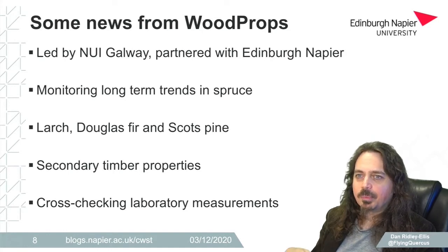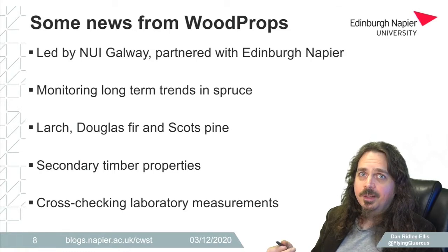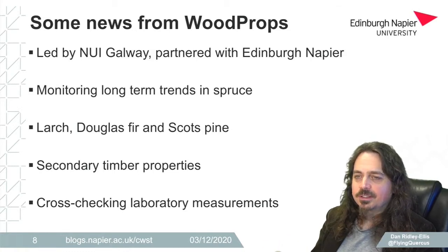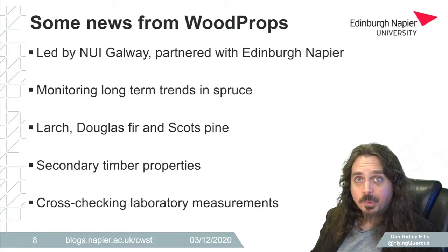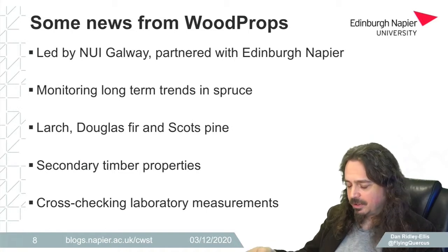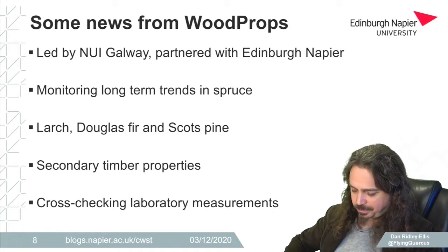And that's an important conclusion for products like glulam, because glulam performance is governed by tension strength. There are some other secondary properties that we want to look at, but it was interesting to confirm what we thought, that the standard editing process had unfairly reduced the tension strength of our resource.